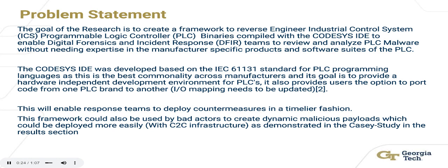The Codesys IDE was developed based on the IEC 61131 standard for PLC programming languages, as this is the best commonality across manufacturers, and its goal is to provide a hardware-independent development environment for PLCs. It also provides users the option to port code from one PLC brand to another. The I/O mapping addresses would need to be updated in that scenario.